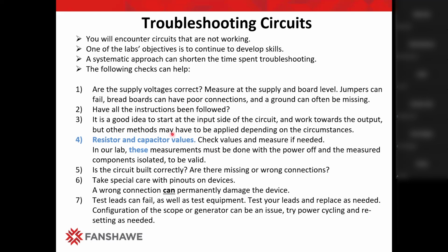All right. Is the circuit built correctly? I know this might be kind of an obvious thing, but it's a good thing to review. Are there missing or wrong connections? It's very easy to make a wrong connection on the breadboard. Take special care with the pinout on the devices.